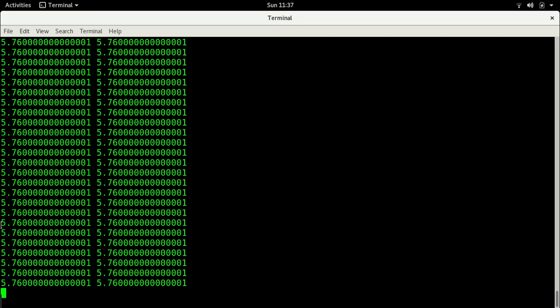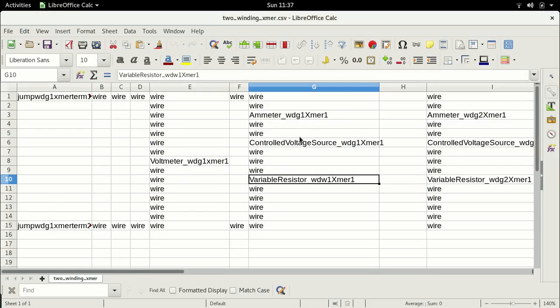You see the two resistances we have chosen, this resistance is a mere 5.76 ohms, right? So we have two voltages with a peak of 350 volts separated by a mere 5 ohm resistance, right? Now, such a system is fairly sensitive, and that could be one reason why we have instability.